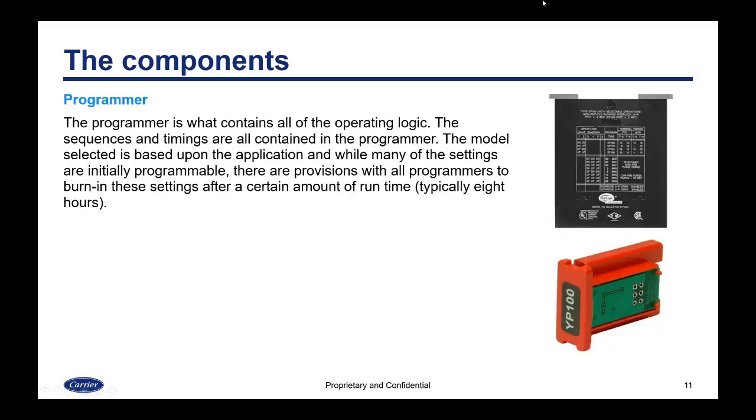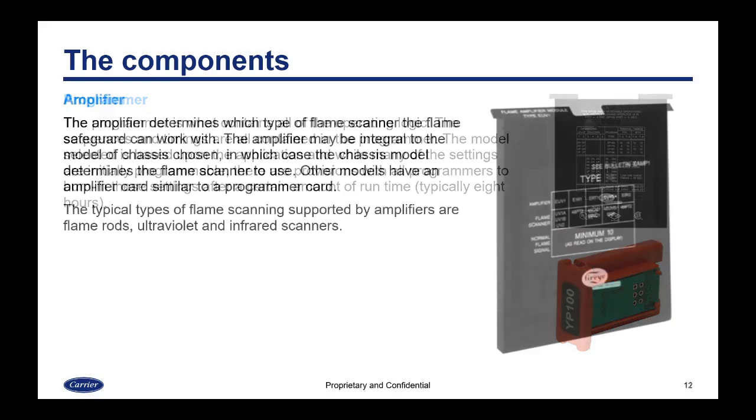The programmer is what contains all of the operating logic. The sequences and timings are all contained in the programmer. The model selected is based upon the application, and while many of the settings are initially programmable, such as timings, there are provisions with all programmers to burn in these settings after a certain amount of runtime, which is typically going to be 8 hours.